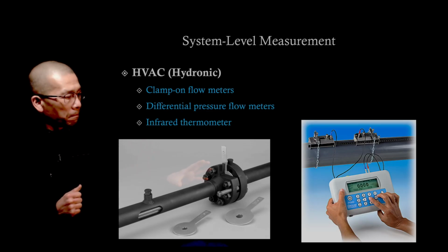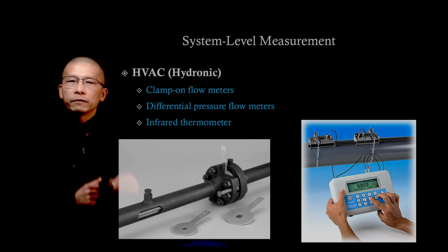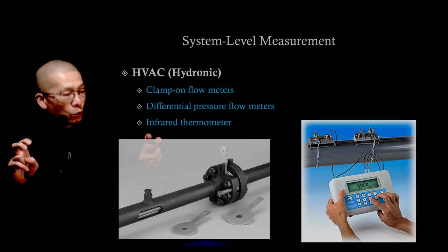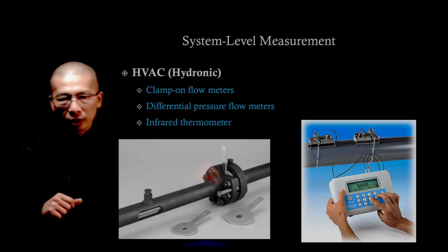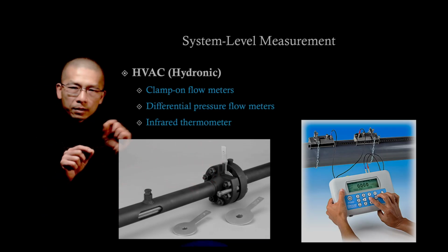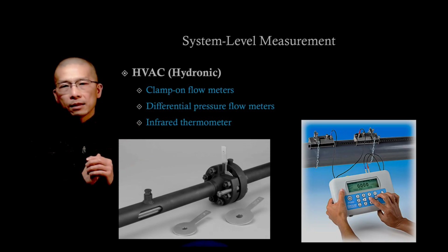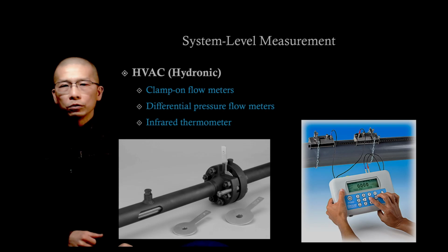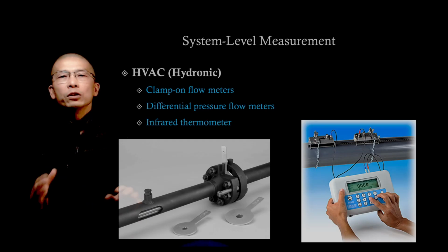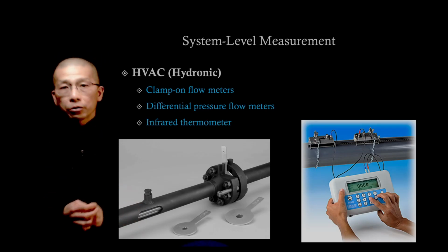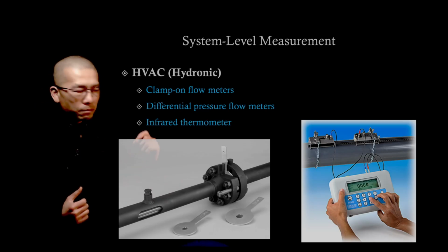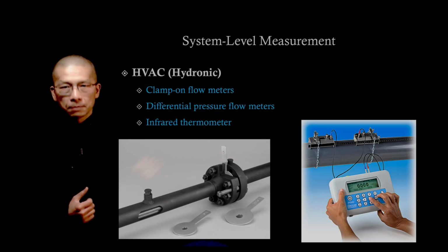And this one here, right, it's a differential pressure flow meter. The reason we use them is the pressure drop across a known restriction, right? We restrict the flow, make it an orifice plate, and the flow is proportional to the square root of the pressure drop. We can calculate exactly how much water is passing through a specific branch of the system. Okay,